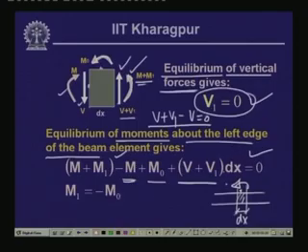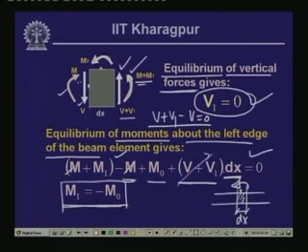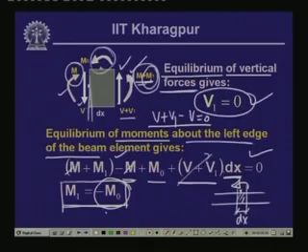Now, if we neglect the terms which are multiplied with the small quantity dx, then we can neglect this particular quantity and M gets cancelled with this. So, we are left with M1 is equal to minus M0. So, this indicates that on the left hand side we had the moment M, on the right hand side of this particular small length dx we have M plus M1, and M is getting added with this value M1, where M1 is minus M0. That means, whatever moment we get on this left edge of the moment, on the right edge this quantity M0 gets subtracted with this value, and finally we get the moment over here.